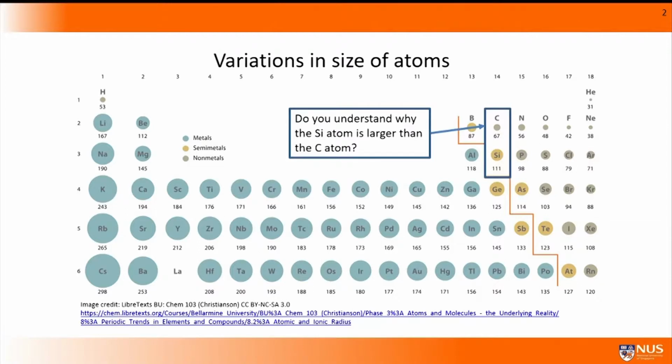So lucky for us that carbon molecules are stable, because it's really handy for life on Earth. Now let's look at the periodic table one more time. Silicon is in group 4, carbon is in group 4, arsenic is in group 5, gallium is in group 3. So it turns out that if you combine gallium and arsenic, you'll get something with the same sort of structure overall as what you get with the group 4 elements, because arsenic has 1 extra electron in its outer shell, and gallium has 1 fewer electron in its outer shell. If you mix them together in a 1-to-1 ratio, you'll get something like a group 4 element in the resulting crystal.